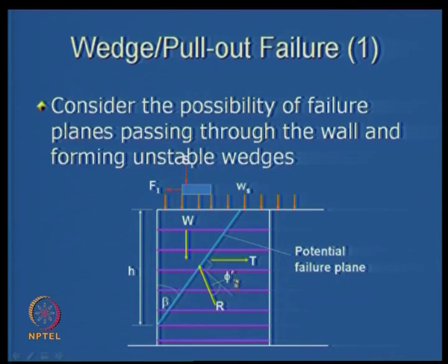They have to be in a position such that the wedge should be stable, which means that the sum of all these tension forces in the reinforcement should be such that it is stable, like the T should be equal to a component of this weight.